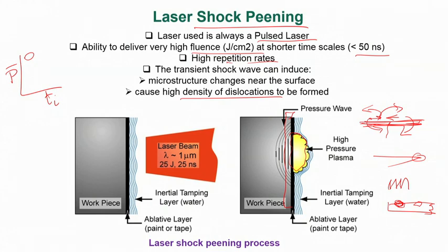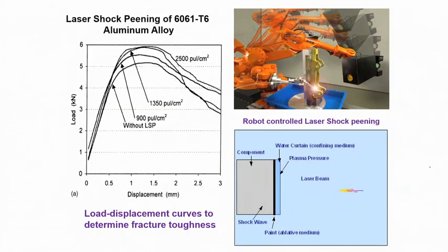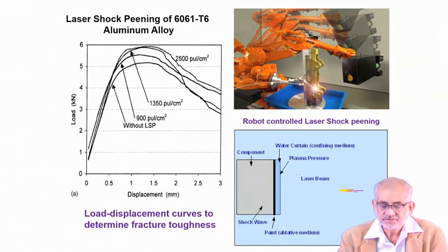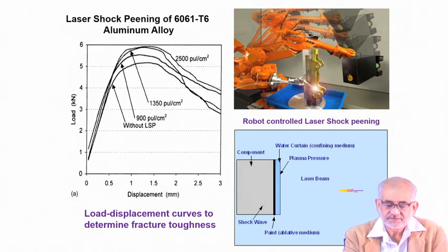So here also you can affect only this very precise corner of the cutting device, or the shear component, or some sharp edges, or maybe the curved portion of the acetabular cup can be given this kind of a treatment to create residual compressive stress. And you can do that very precisely, exactly at where you want, and avoid heating other zones where you don't want. So this is the advantage of such kind of shock peening,